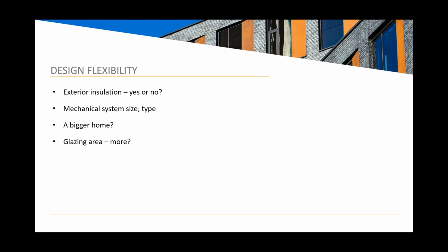Exterior insulation on concrete buildings, yes, and steel frame buildings, yes, you'll need some exterior insulation. With wood frame buildings, maybe not. Maybe a small upgrade to triple glazed windows can outperform the original design that included exterior insulation and allow you to remove it. So you can save money and cost and wall thickness, et cetera, with changes like that.